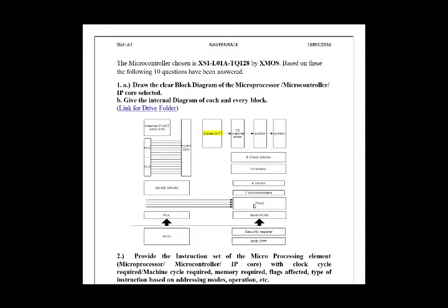So we just spoke about the OTP register, right? So what is that OTP? It's an 8 KB one-time programmable memory along with a security register that configures system-wide security features. The basic security features for the whole microcontroller are configured by this OTP. It holds data in 2K rows of 32-bit configuration.